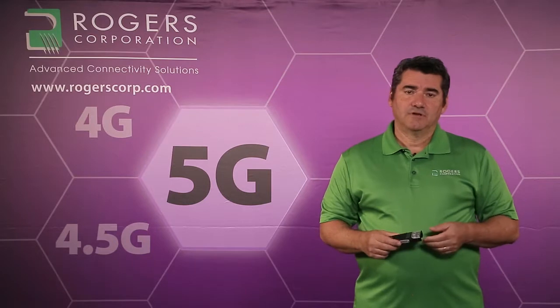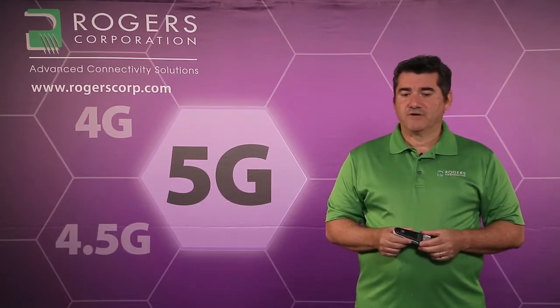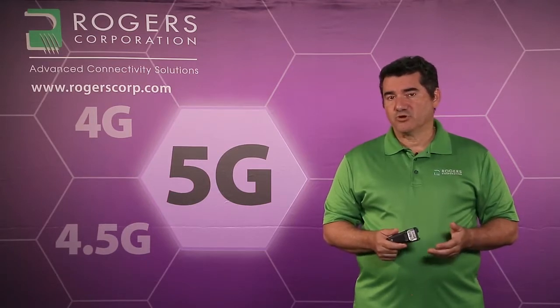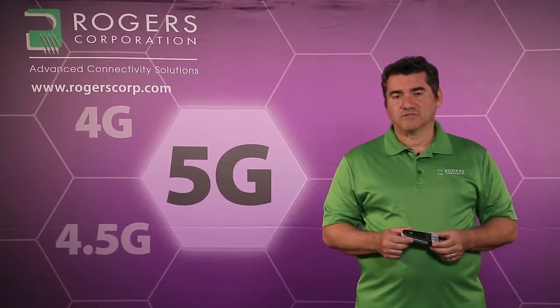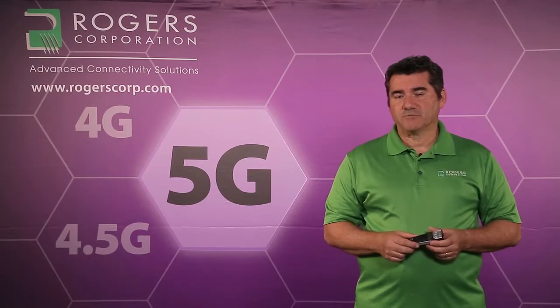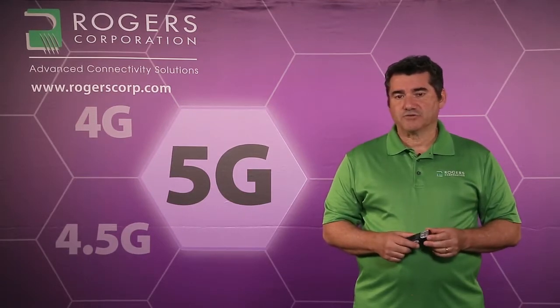So what do we have? Rogers has multiple materials that are considered high thermal conductivity, varying in degrees from dielectric constants of 3 to even 6.15, like the RO3006. This is to reduce the size of some of the amplifiers for lower frequencies. So let's compare some of these values.